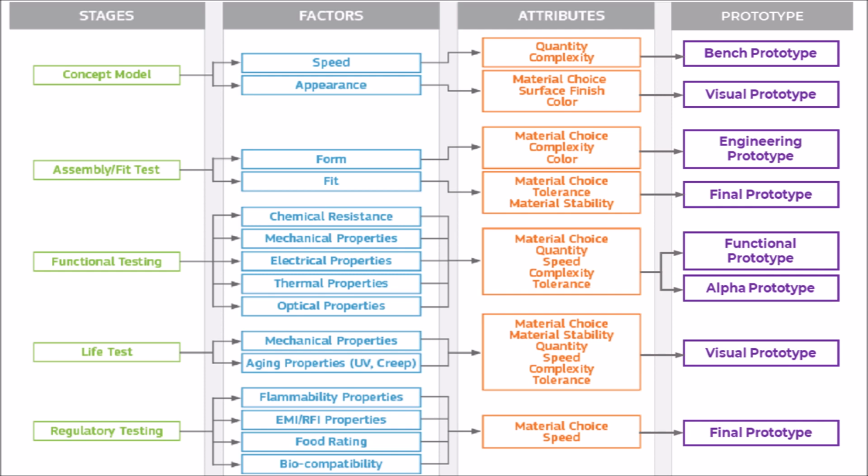Regulatory testing. This testing stage is signified by a regulatory or standards organization or agency to assure parts are suitable for a particular use, such as medical, food service, or consumer application. We need to test the flammability properties, EMI, RFI properties, food rating, and biocompatibility of the product in this stage.